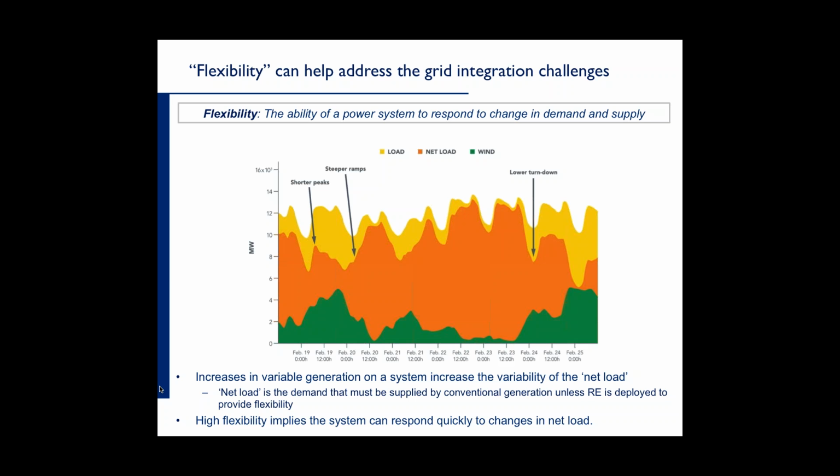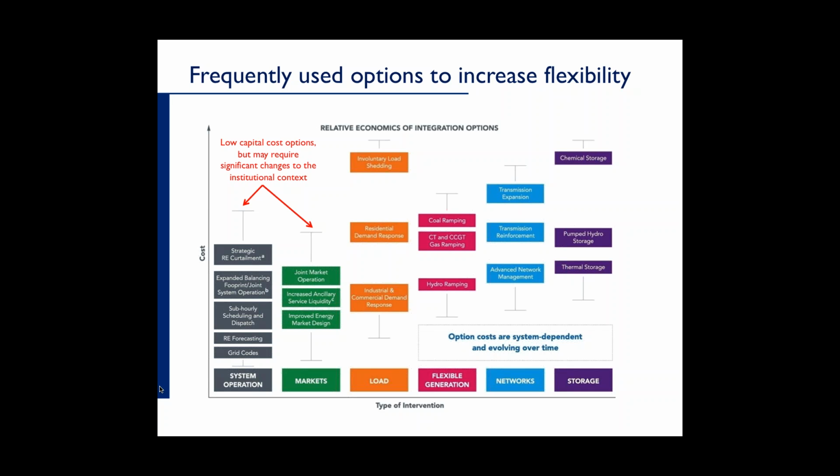So that means that if I have a lot of coal units or gas units, in order to take advantage of all this wind energy, I need to be able to reduce the generation from my coal and gas to 5,000 megawatts now, whereas in the past, with no wind, all I had to do was reduce the generation to about 10,000 megawatts. So these are some of the key challenges with respect to the variability that the power system operator is faced with. And of course, the question is, can we manage this increase in flexibility? And the answer is, well, yes, there's a lot of tools.